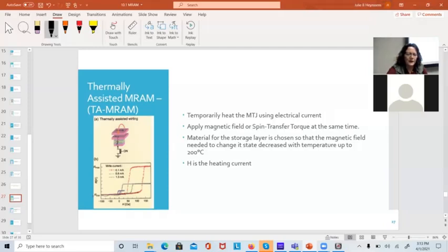It takes a higher H field to flip it into its high state than my normal operation. Now, if it's already in its high state, it's going to take an even lower H field before it flips. So if I read it in between here and here, it's not going to flip it. I can just read the resistance without flipping it by putting it in between there.